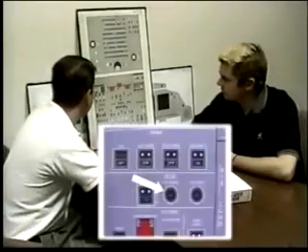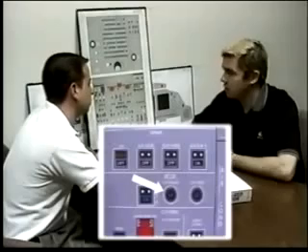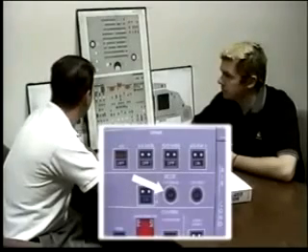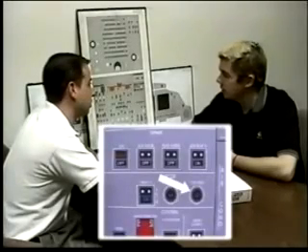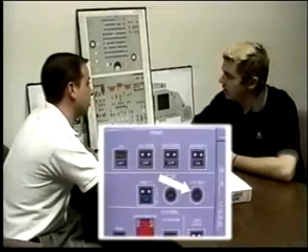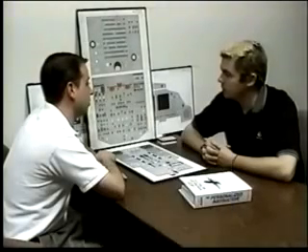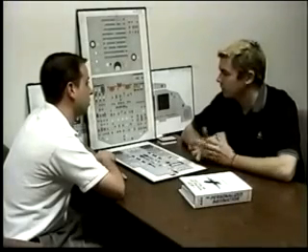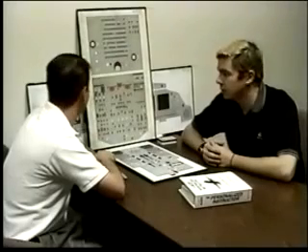How would you use the CVR erase switch? Just have to be on the ground with the park and brake set. What about the CVR test? You need to be on the ground, park and brake set. You need to have the power to the CVR so that way it can do its little test.